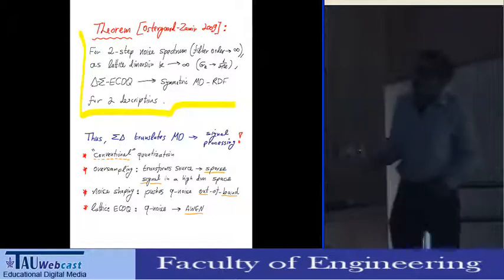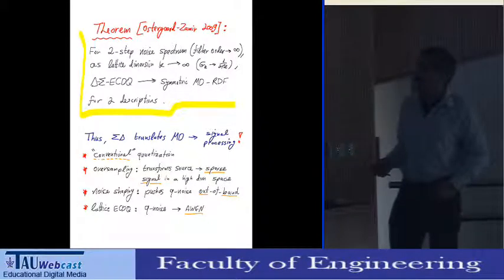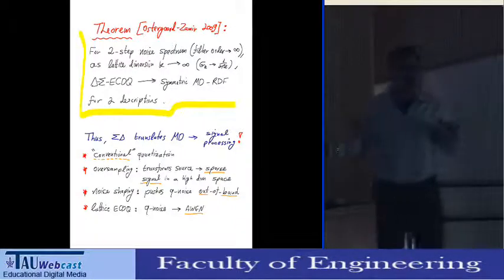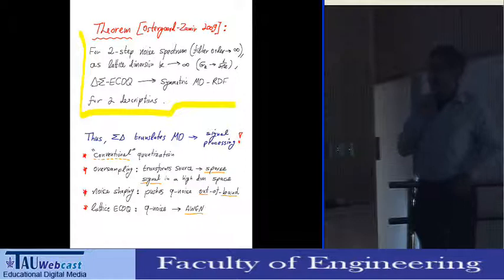The result says that if I'm using this two-step filter, which requires an infinite-order predictor or filter, and if I'm taking the dimension of the lattice in the ECDQ to infinity, then this delta sigma ECDQ scheme achieves the optimum performance for symmetric multiple descriptions. So I'm closing completely the gap to the optimal performance.